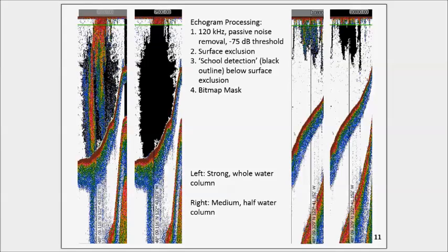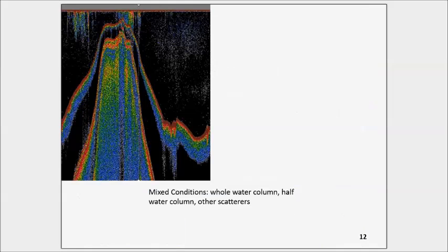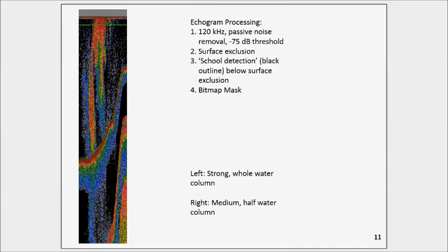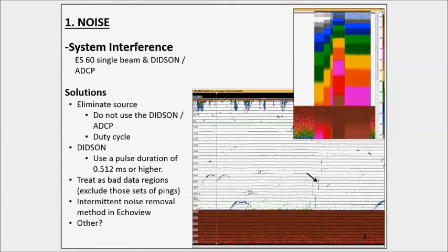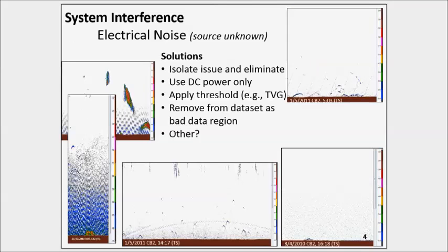This is Daniel Dan from PNL. Yeah, we were just touching on electrical noise. We have the same experience. We do a fair amount of work measuring noise in the forebay of a dam and also in the tailrace. And of course, a lot of the sensors are a combination of active acoustics and passive acoustics, but they share similar issues with electrical noise and some of the air bubble entrainment due to turbulence. What we found out is DC power is always your best friend.